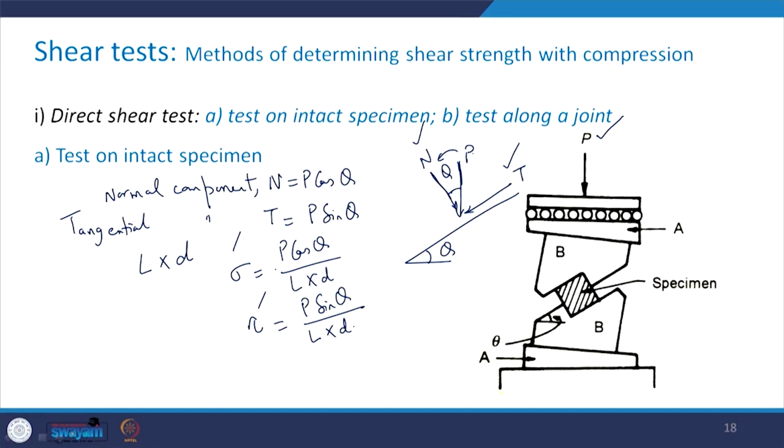So, what we do next is we can plot, here is tau and then here you have sigma. Whatever is the value, let us say I have conducted say 5 tests. So, it looks as if a line will fit here. Accordingly, if it is following the Mohr Coulomb criterion, I can find out the shear strength parameters like this from the test results.